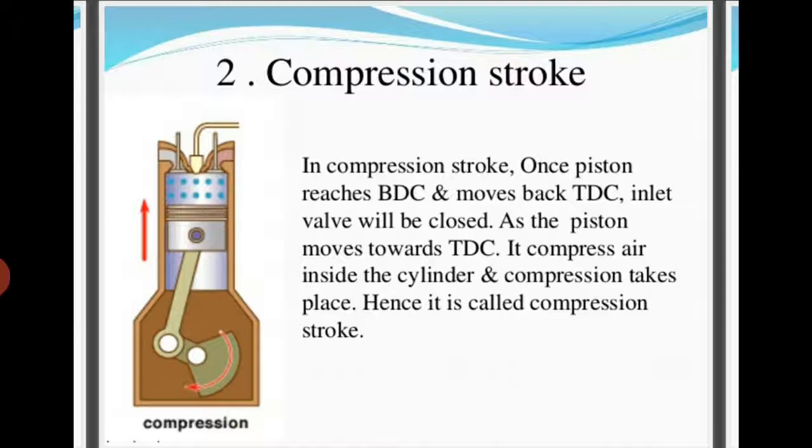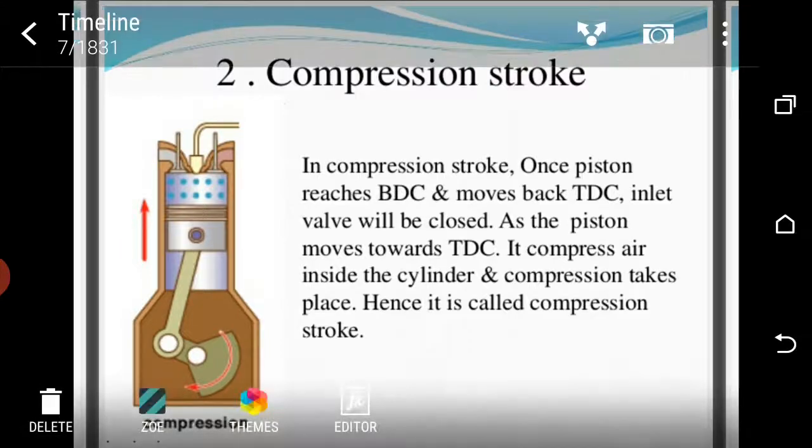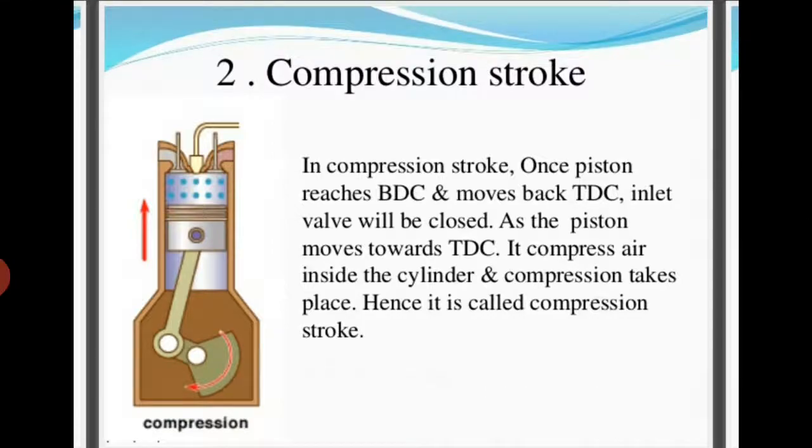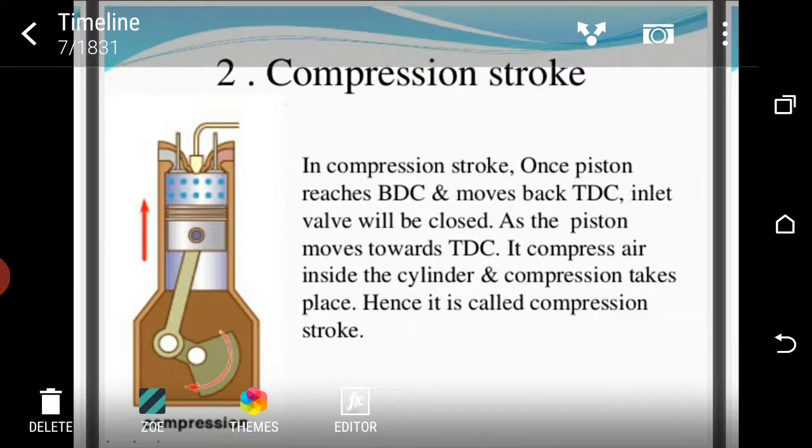ignite the fuel. At the end of the compression stroke, a fine spray of fuel is injected by the fuel injector into this hot air. Now this ignites the fuel, and injection of the fuel takes place at constant pressure. When the ignition of the fuel takes place, a very high pressure is generated.